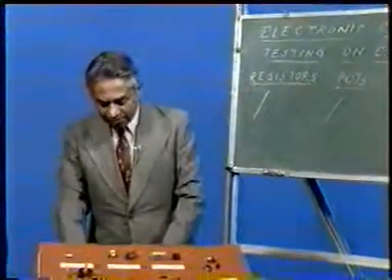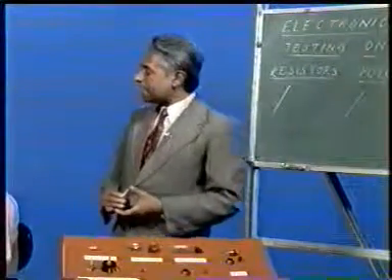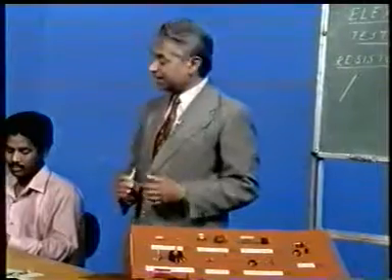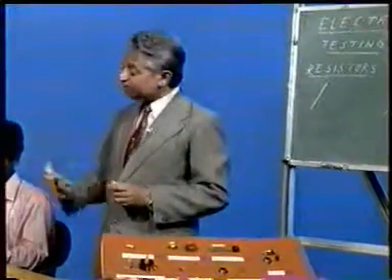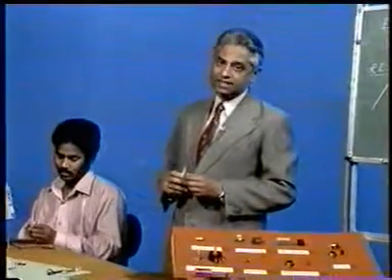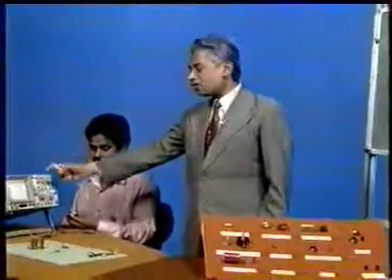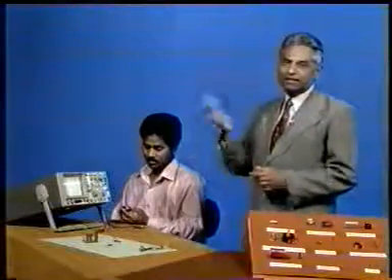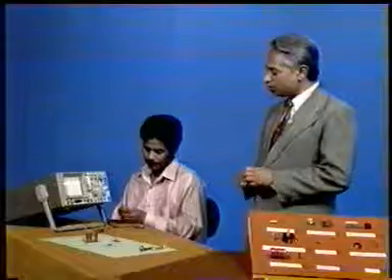But before I go for the checking, I would like to tell you that you have to keep this CRO in component testing mode. If this facility is not there in the CRO, you will not be able to conduct these tests. So first of all, the CRO must have the component testing facility, and then you have to keep it in component testing mode. What do you do for that?